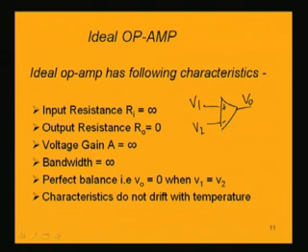Now, this perfect balance will come only because the differential amplifier, which is the basic circuit inside the op amp, has transistors which are perfectly matched. So, when the two transistors are perfectly matched or balanced, we do not have any unbalanced voltage, and that means when these two voltages V 1 and V 2 are equal, there should not be any output voltage, that means the output voltage should be 0. That is to be maintained for the op amp, that is one criterion.